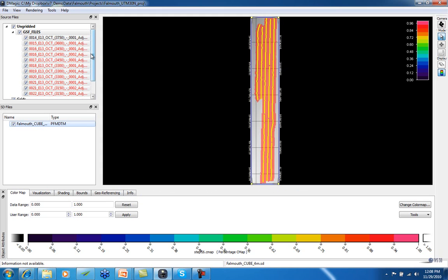It's really reading the metadata for those files because the metadata has changed. There's some points that are no longer part of the file. They've been marked as rejected. Once they all come in, a way that you can validate the PFM unload is to grid the surface using the shoal bias algorithm and the deep bias algorithm, and that will confirm that all of the outliers have been rejected. So I'll go through that once the scanning is complete.